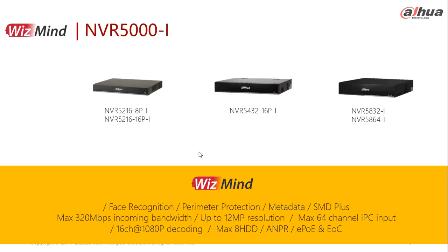So apart from the AI functions, this one has 8 PoE. So the ePoE technology is also employed in the AI series. The ePoE technology is where you have a cable running, not using just the standard 100 meters Cat6, you can have cameras installed even up to 800 meters, and you have the NVR from this side powering the camera at 800 meters.